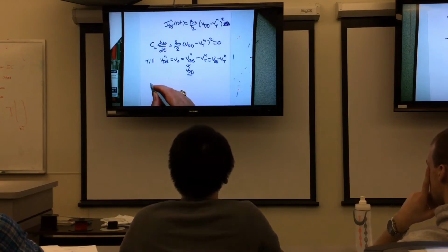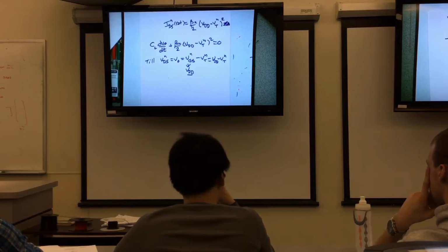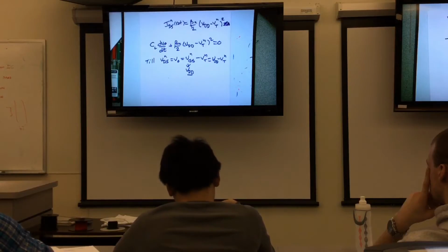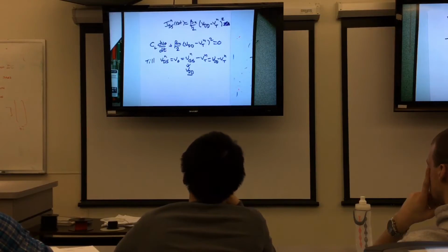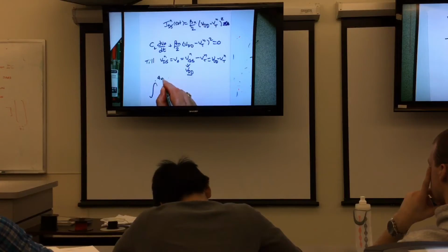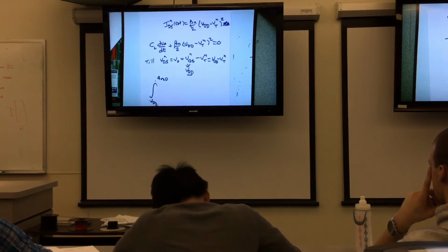And what I'm going to do is adapt the notion that we're only going to be starting with the initial output voltage of 0.9 VDD, 90% of VDD. So there's a little change here. And so we're going to start out at 0.9 VDD, and this is going to go through the transition point.